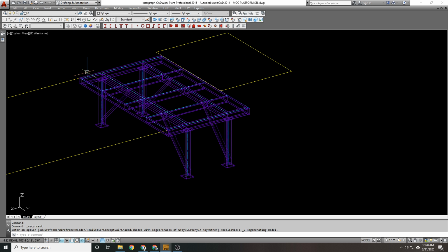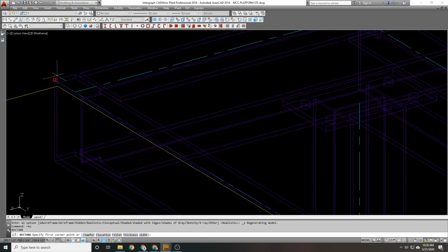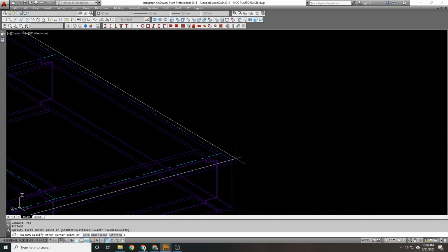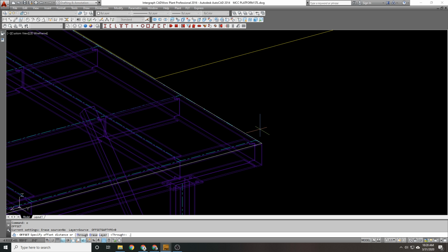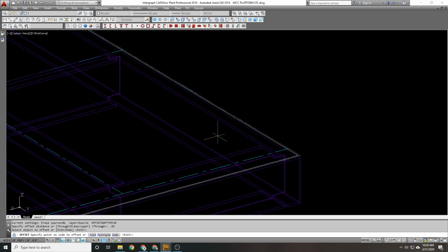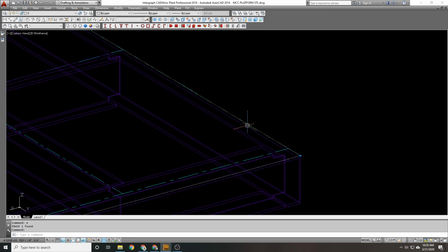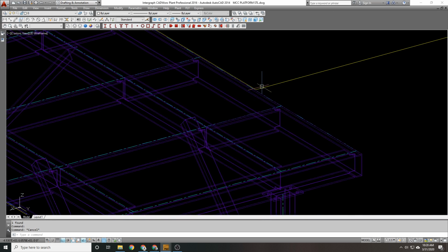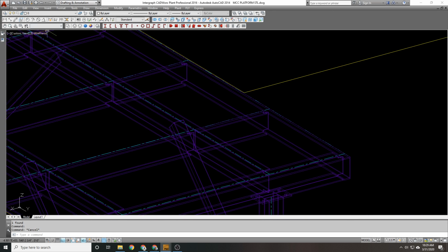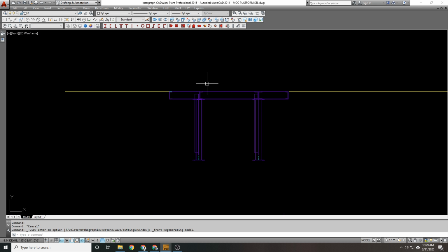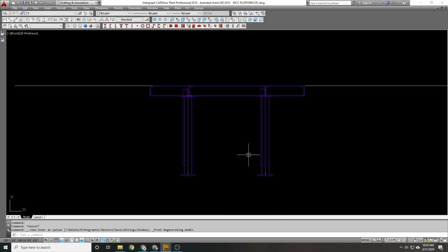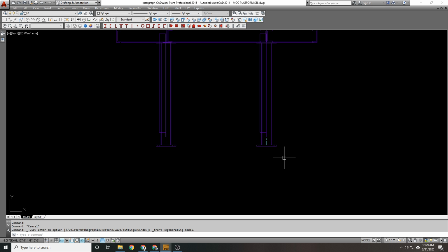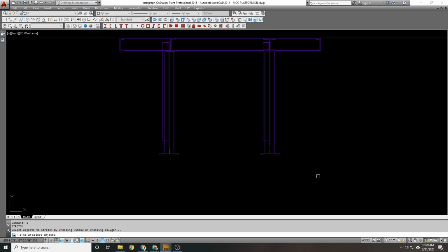This is optional depending on your company. Some places may only do just a rectangular solid offset 1/4 inch. And actually, before I do this, I just realized something. The top of my walking surface in these buildings is at this elevation, and I set my steel there. So here's what I'm going to have to do. Look at this thing from the front and stretch everything down 1 1/4. I want to say in this case, it's probably easier for me to stretch this up 1 1/4.